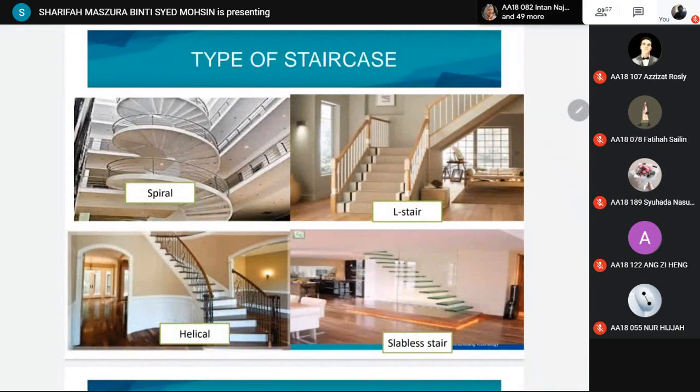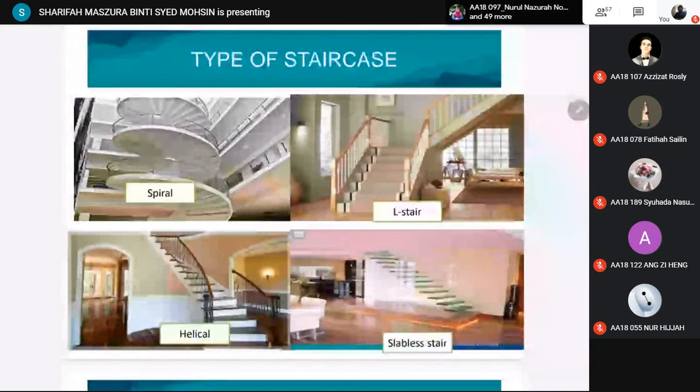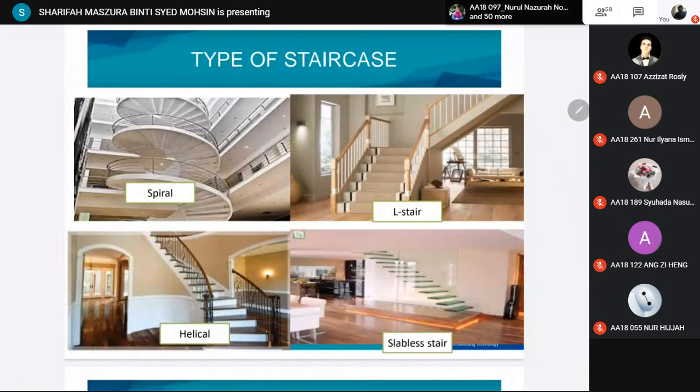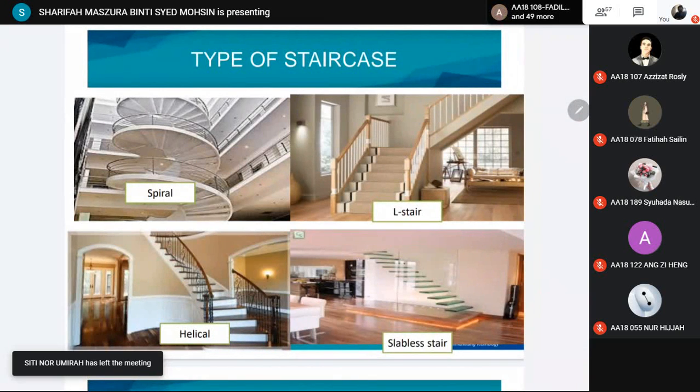So we have to know how the staircase is going to be supported. Usually you decide on your own how it's going to be supported. Otherwise, it is mentioned inside the architectural layout. If not mentioned, then you can decide where you want to put the support and then design according to that.